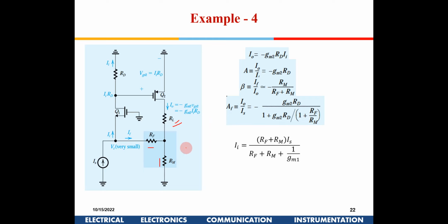Voltage is divided here. No, it is actually, if you see here, this is the output current, right? Depending on the ratio of these two resistances, one current will flow here as feedback. This is one current which is going into this. This is another current which will go from here. A fraction of IO will go here.